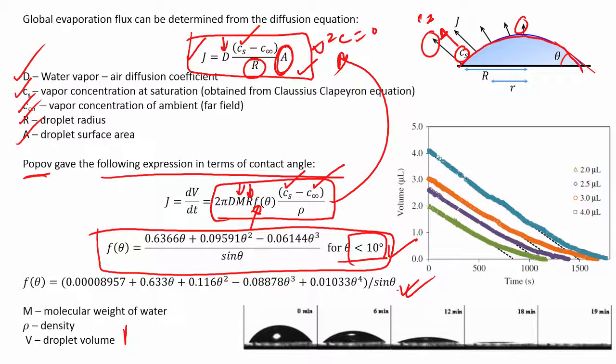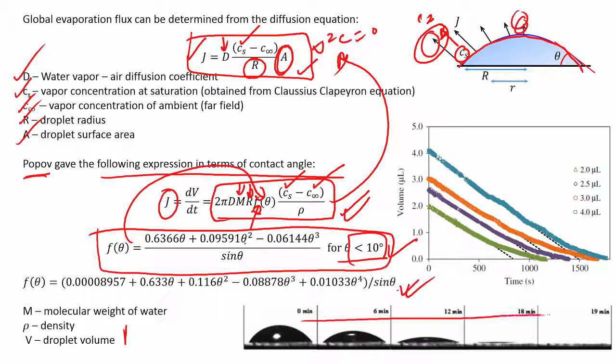For a wide range of contact angle you can apply this expression. You can just compute the instantaneous contact angle, plug that instantaneous contact angle in here, and calculate the global evaporation rate. Remember, this is the global evaporation rate, this does not take into account whether evaporation is happening more here and less there. This is a global factor that people have assumed. As you can see, this is a time marching of the droplet. The droplet virtually remains in a constant contact radius kind of situation, and you see that it slowly evaporates and ultimately goes down.